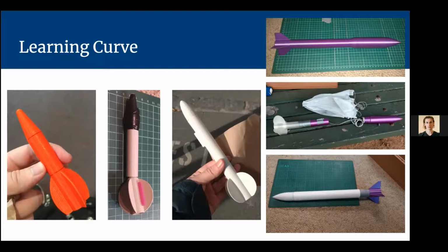Basically this was when I was just learning. I hadn't done many OpenRocket tutorials online, I hadn't looked up YouTube videos or anything like that. I had learnt CAD and a little bit of OpenRocket, and I just went for it, and it was good fun, honestly. It was a good learning experience. So that was my first ever design. It spiraled out of control as soon as it left the launch rod because I hadn't checked the stability over time.